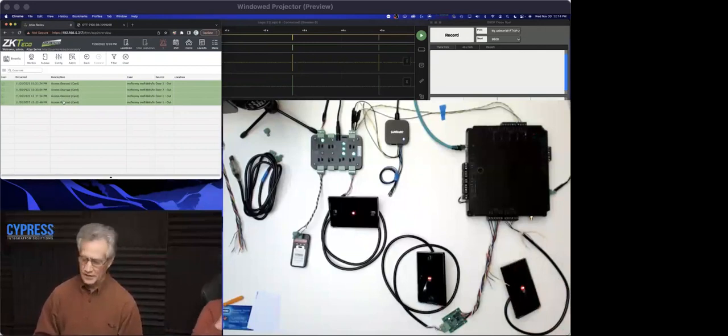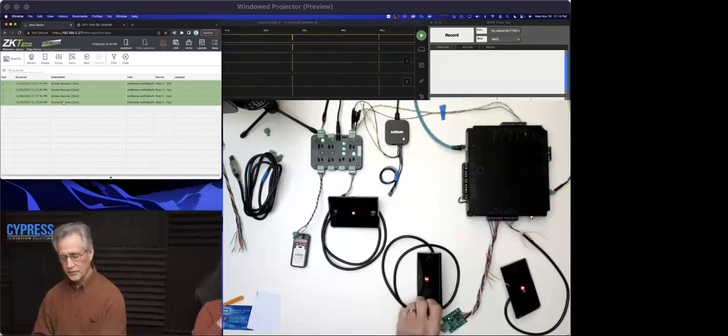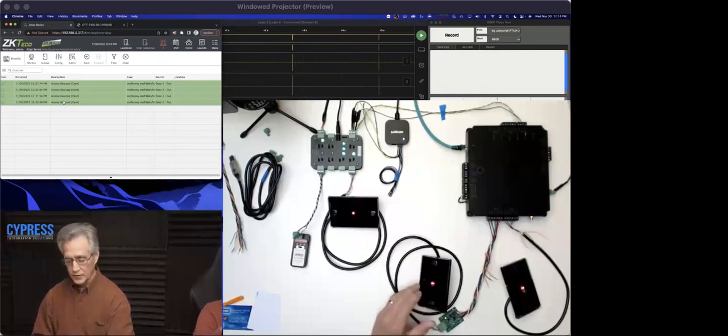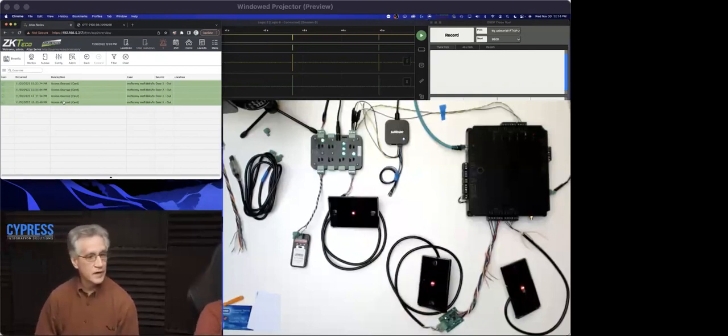So as far as the panel was concerned, that was connected to a Wiegand reader, and that's to make it very easy in the field to retrofit. But the beauty is outside of the door, or on the vulnerable side, the attack side of the door, you've got OSDP and its encryption and authentication.